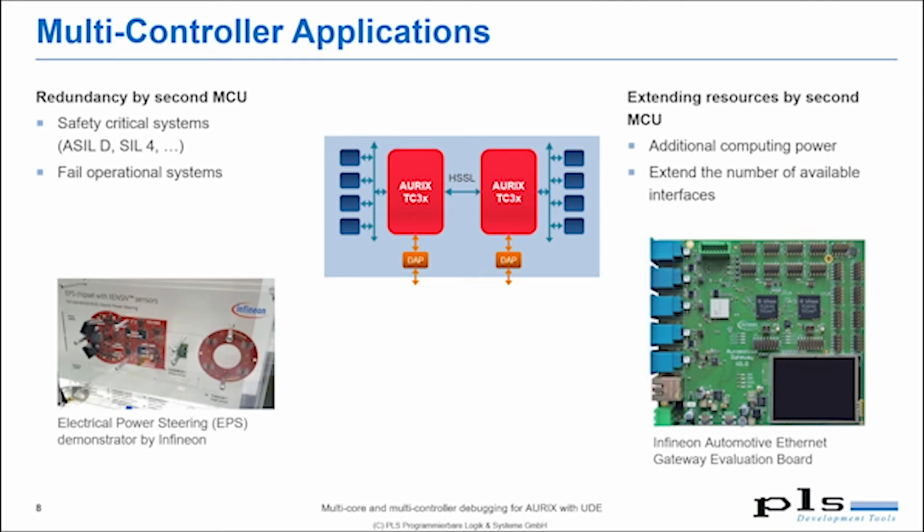The other scenario that we have has the same problem. It is an application that is running on such a gateway board from Infineon. Here we have also two AURIX MCUs used, but not to get redundancy, but for extending the available resources, like adding some interfaces, adding some computational power and so on.